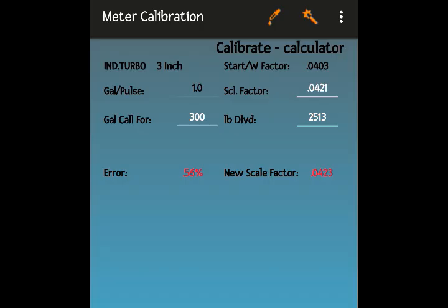In our next calibration illustration, we will use the volumetric capabilities of the application, which utilizes graduated cylinders. We will choose a RCDL 5/8 inch meter to calibrate for 4 ounces per pulse to within plus or minus 3% accuracy.